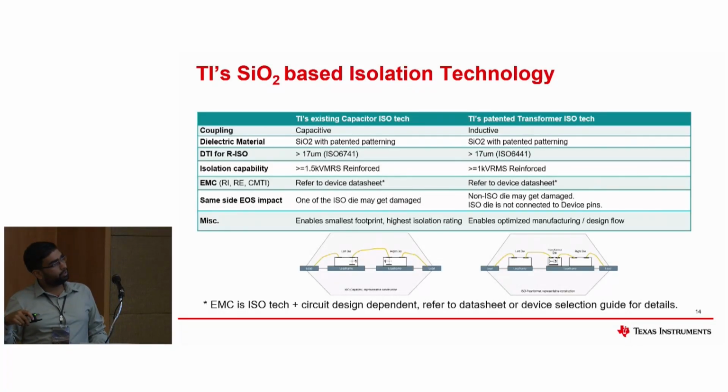Second, it helps us reduce the cost of the overall solution. This might look like two dies, but the high voltage constraints inside the die make it more costly than designing two smaller dies and having one isolation die separately. Only here the cost that increases is the two bond wires from each side.